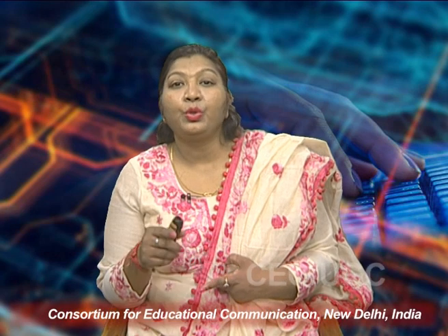The main advantage of the rewirable fuse is that it can be rewired easily in case it is blown due to a short circuit or overcurrent which melts the fuse element. Simply put another wire of the fuse element with the same rating as before and it will work in the same manner. So the rewirable fuse is very cost effective and used in many appliances.